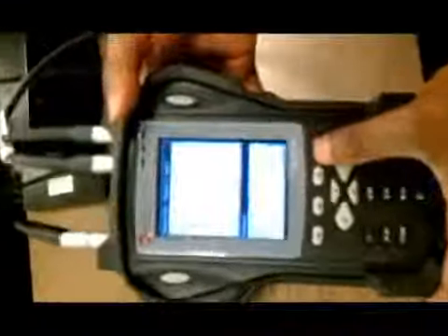So it's asking us if we got our accelerometers on plane 1 and 2. We'll hit OK. So we got our readings now. Since the light has turned green, we can hit our fire button to capture the readings. And what it's going to ask us now is how much weight we're putting on it, what angle, and the radius that we're putting it at.